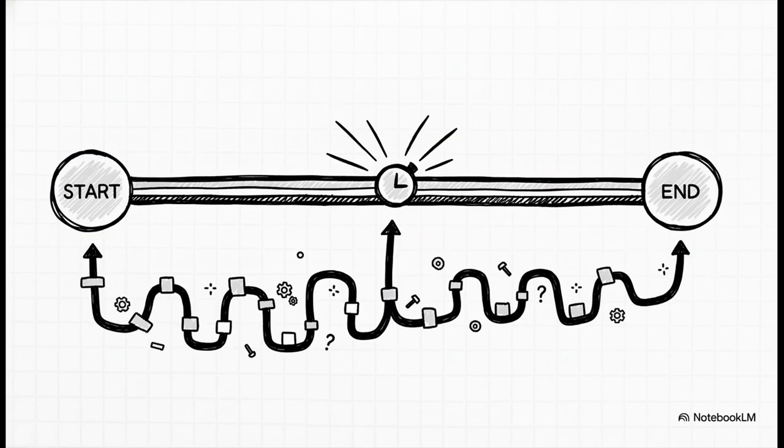Oh, and we all love a good engineering shortcut, right? Check this out. If your base voltage happens to stay exactly the same, meaning your old base voltage equals your new base voltage, that whole voltage chunk of the equation just turns into a 1 and disappears. In that case, you only need to scale your impedance by the ratio of the new base apparent power over the old base apparent power. It saves an absolute ton of time when you're working through a massive schematic.